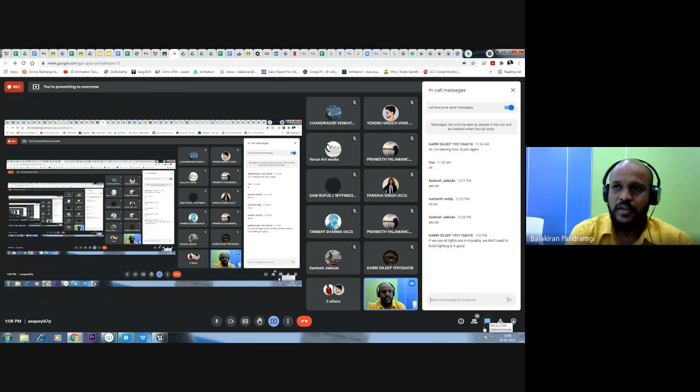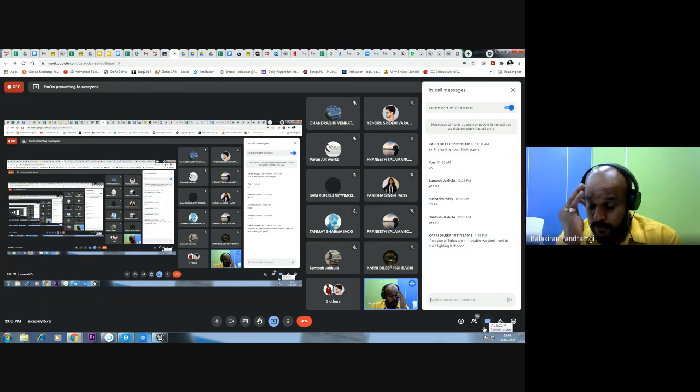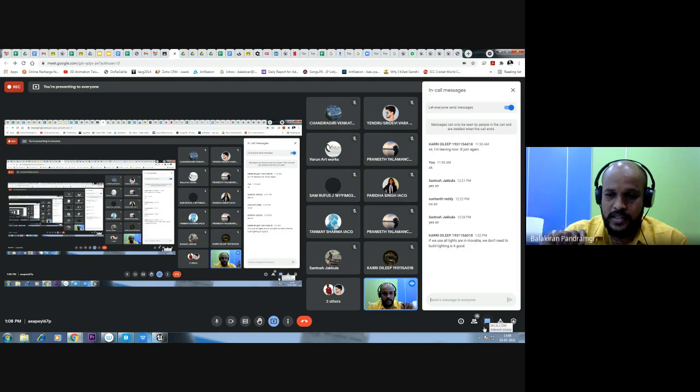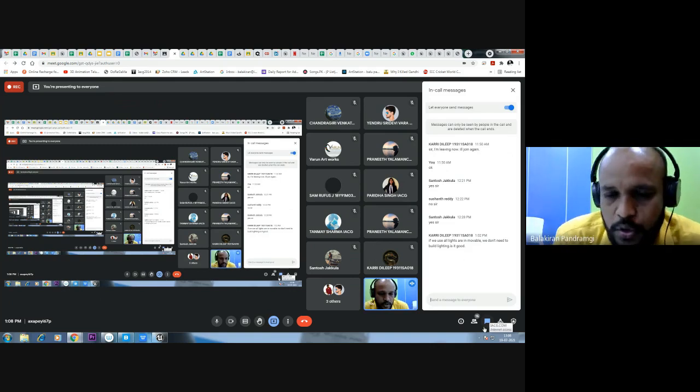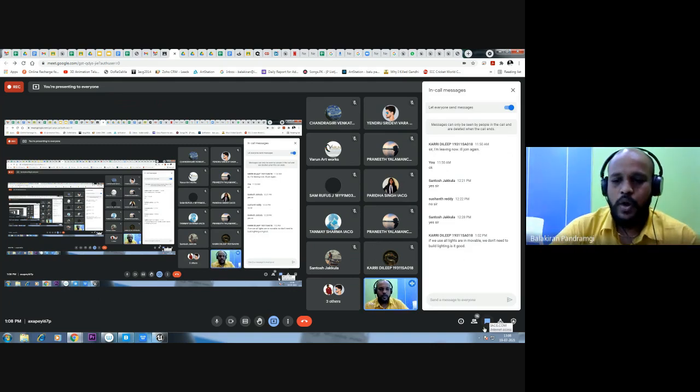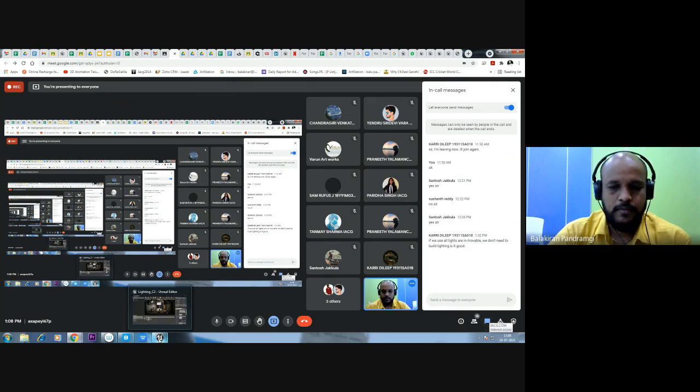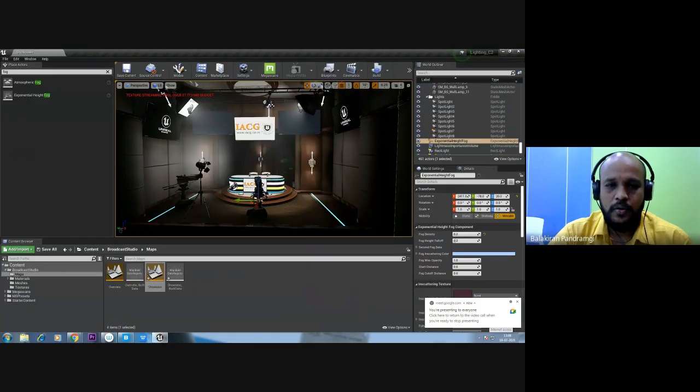But the problem is, when you run the main scene, what happens? Each and every light will be rendering each and every moment, and it will become dynamic. So it will take more time. At the same time, when you go static, your light quality will be more than dynamic. If you try, you can observe it.